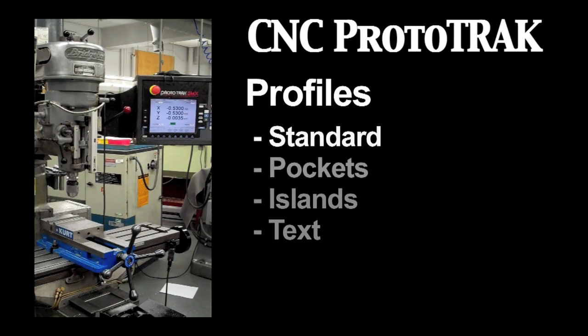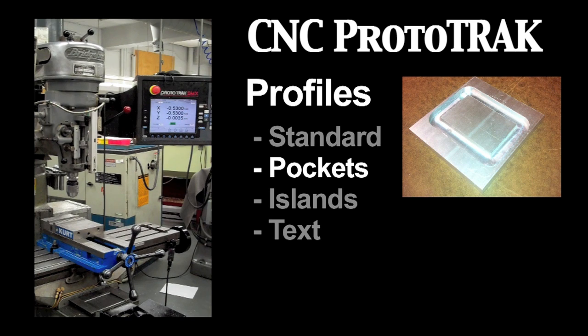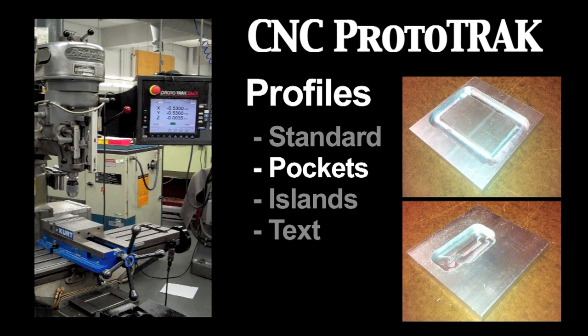Now we'll learn how to make pocket profiles. A pocket is the negation of a profile. Instead of specifying a region that the ProtoTRAK will cut around, the specified region will be completely excavated by the ProtoTRAK. All of the specifications for pockets are identical to standard profiles. However, there is one important factor that you must keep in mind.